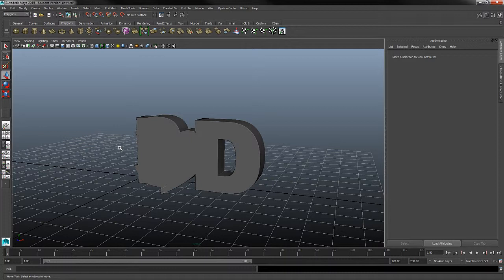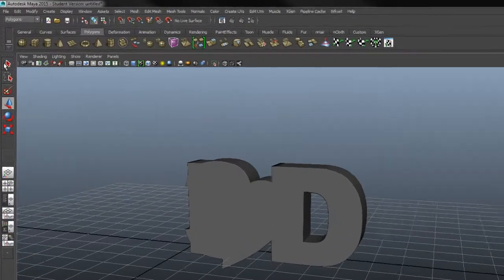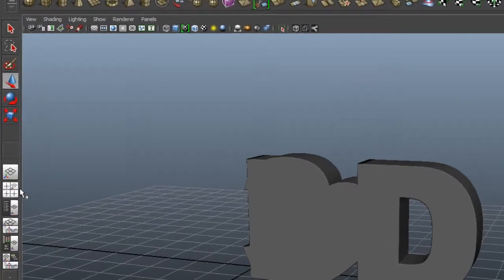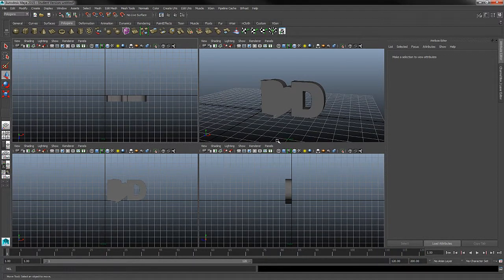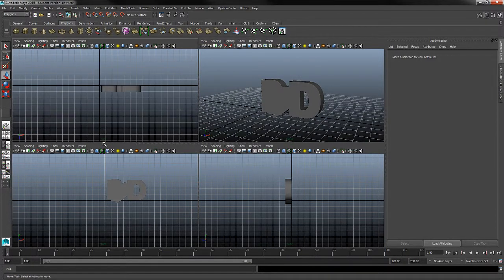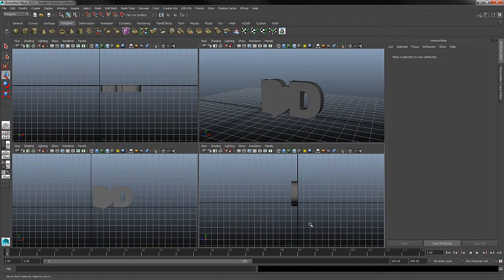Now, one tip before we move, rotate, and scale is that it's advised to always do this in a two-dimensional view. Currently, we're looking in a 3D environment. So let's take a look at how we can set up two-dimensional views. It's very easy. We can come over to our toolbox, which is this left-hand panel, and our default is a perspective view. We're going to switch to a 4-view layout. Now that we have geometry, you can immediately see what this is doing. Here we have our 3D perspective view. We have a top view, and look for the name in the lower center of each panel to see which view we're viewing. So we have a front view, and then finally a side view.